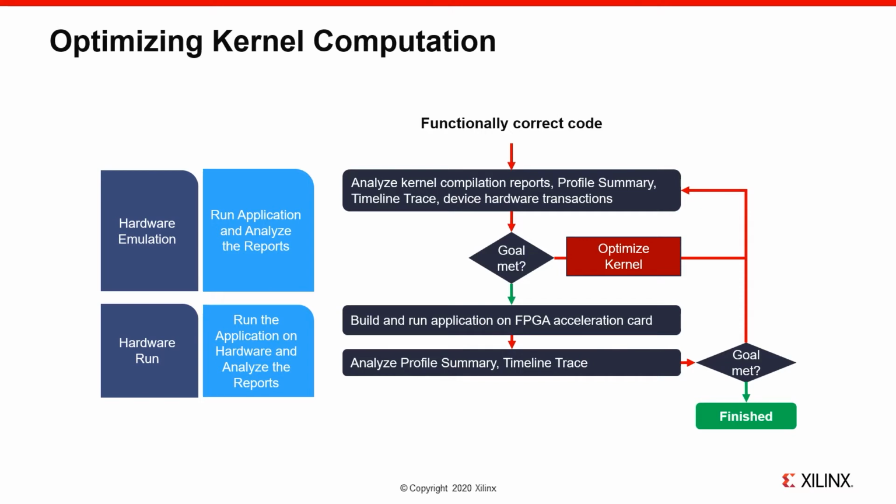That is, the kernel can receive and process data on each clock cycle. Optimizing the initiation interval is generally achieved with techniques such as pipelining, loop unrolling, and array partitioning. We optimize the hardware design to meet the requirements of the data path.